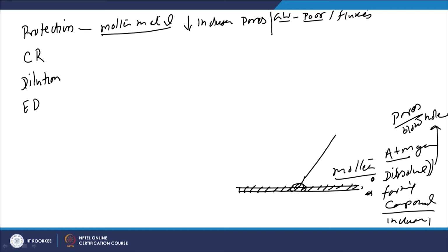In general, it is poor, and this happens primarily due to the higher oxygen and nitrogen concentration in the weld which is produced. While in the case of the shielded metal arc welding process, it is the thermal decomposition of the flux coating that leads to the formation of inactive gases, a gas cover all around the pool.